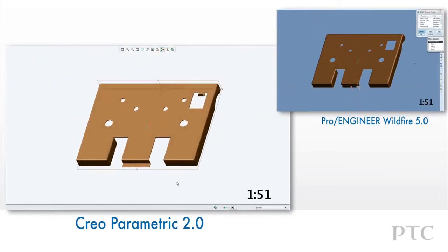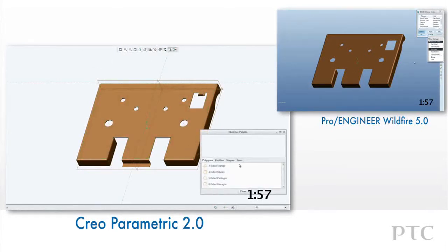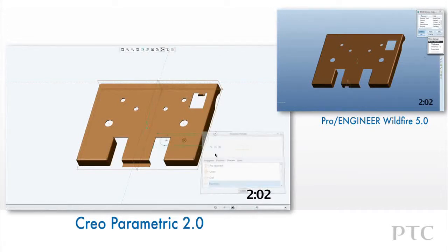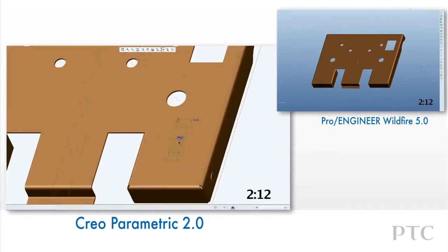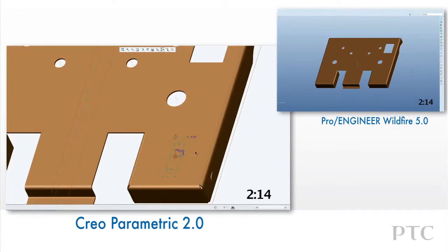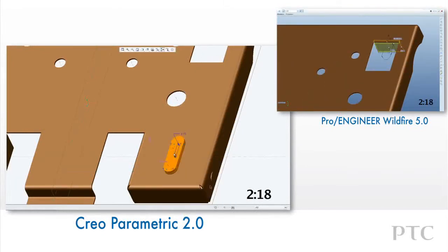Lastly, we can sketch another form by adding a racetrack section and then dragging the depth to the desired value. We can add taper and then ensure that we add rounds in the form and the intersection of the form and the walls. In Pro Engineer Wildfire 5, we would have had to create a separate form part to accomplish this, or a quilt with the draft geometry already built in prior to creating the form feature.